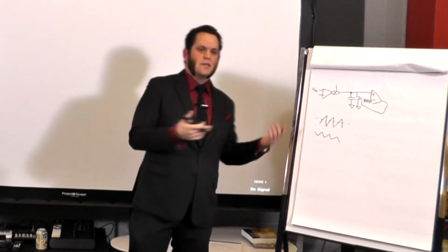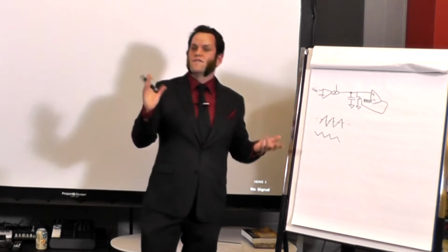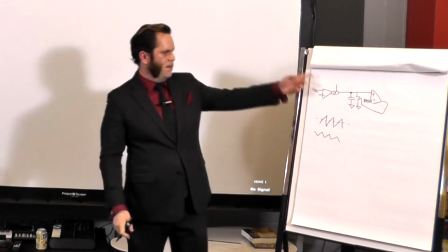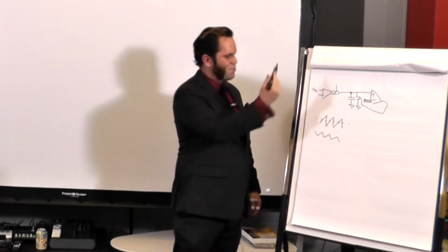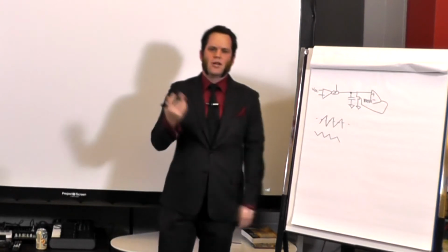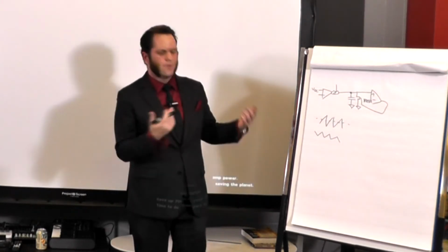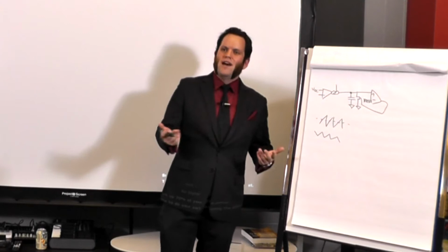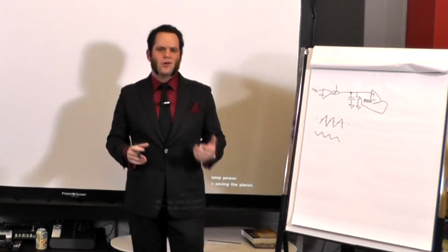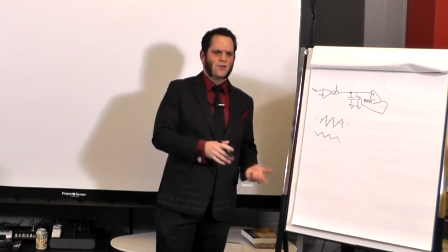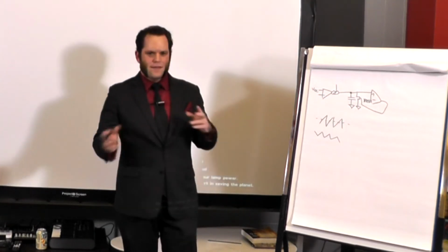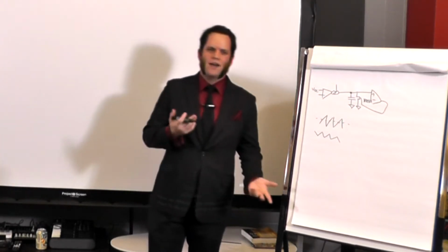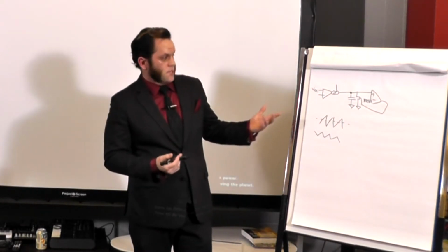So there's some really easy ways to take that sawtooth wave and then do other fun things with it. Depending on this, I've been doing the ramp up example, but if you shift your signs in your control voltage or your control current, you can do the ramp down example. It doesn't matter too much with your audio band VCOs, but if you have a nice low frequency oscillator doing a filter sweep for you, then suddenly the direction of that sawtooth matters. So you have some choices there.